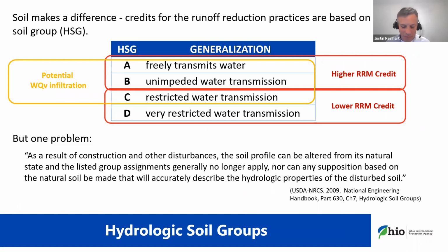The one thing that maybe, in going through this quickly to make time, I didn't elaborate on, but is a key component of that, is the soil. Now, what do we have as far as ability to infiltrate water? And part of that hydrologic model, all of you are aware, we have hydrologic soil groups. So we have all of our hundreds and hundreds of soil types or soil mapped units that are based on texture, depth to groundwater, depth to impervious layers such as bedrock, all rammed into 4 very broad categories that give some crude estimation of how much rainfall is converted to runoff and how much is actually able to infiltrate and transmit through the soil profile. So we have our A, B, C, and D soils.